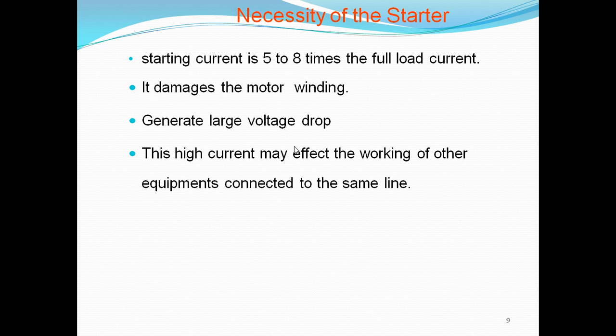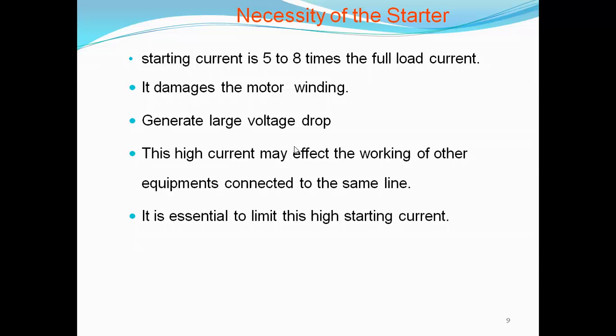For them also the supply is interrupted and disturbed. Because of this high starting current, the other equipment is affected. So starting current is 5 to 8 times the full load current. So we have to limit this high starting current.